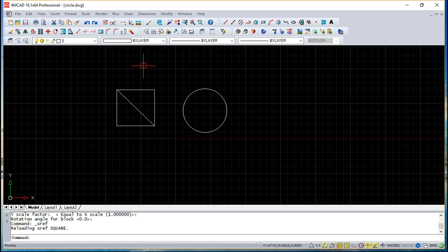So this is the idea for the external reference. This is very important because, for example, you may have a group of people working under the same drawing. If you make this main drawing the base one in some place and everybody is working on that same drawing, then you can get these more or less automatic updates through this instrument, which are the external references.